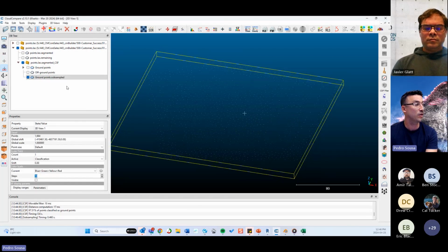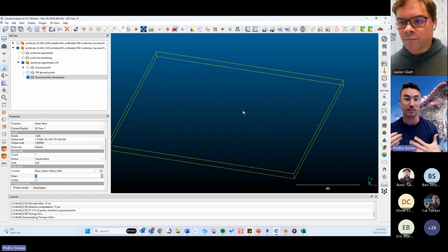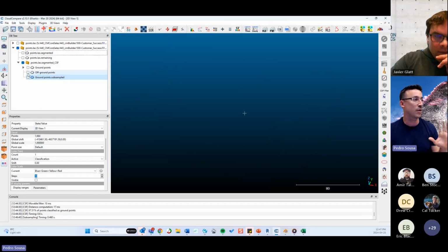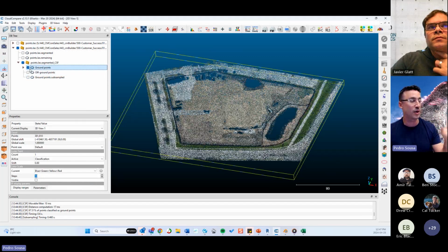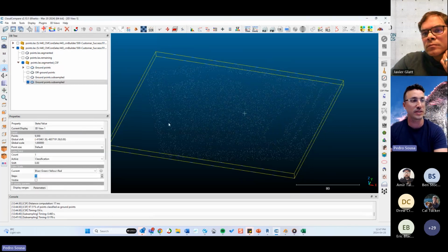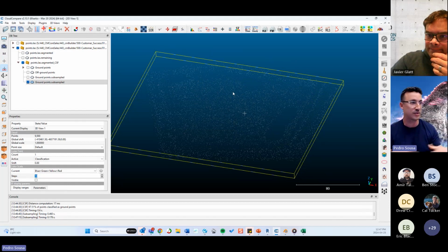But sometimes even when you do that, let's say that I put over here 4 meters and I hit OK, you might still have more points than you can use. So you might still need to do other types of subsampling, right? In this case over here, this subsampling gave me almost 2000 points. So let's say that I want to keep my resolution a little bit higher than this, and I want to focus on getting the maximum resolution that I can. So I'm going to go into my subsampling, and I'm going to go into random, and in the remaining points over here, I'm going to type that I want to keep 9000 points. So this will randomly remove points from that surface to keep only 9000 points.